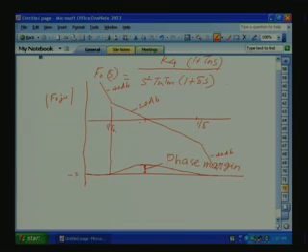Now, we have to design our Tn such that it crosses the gain crossover frequency at minus 20 dB per decade, and you should get sufficient margin. So, this is in log scale. The usual practice is to choose the crossover frequency omega c, that is omega c here, at the geometric mean of the two corner frequencies.